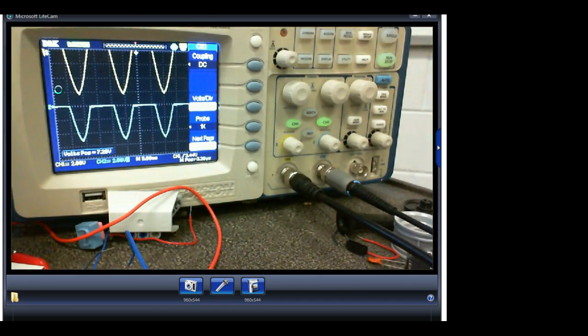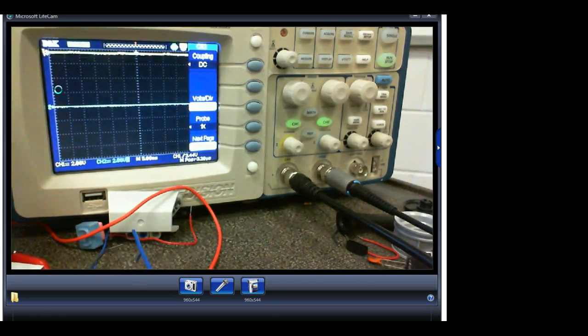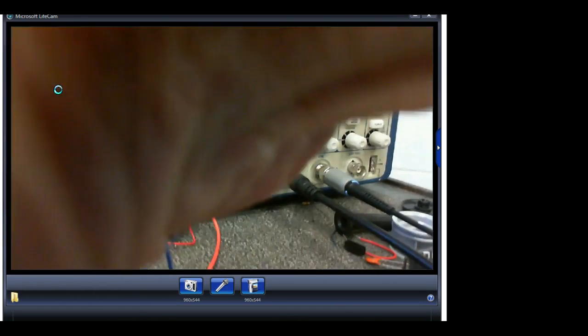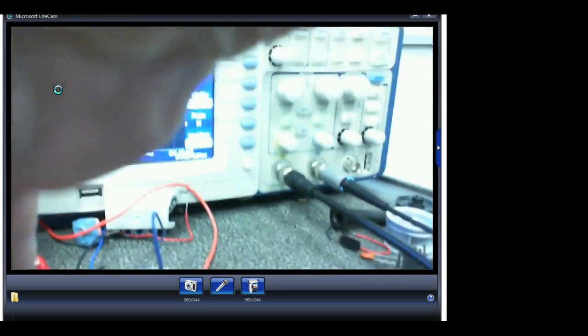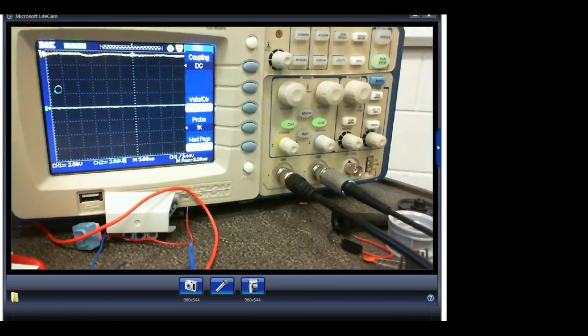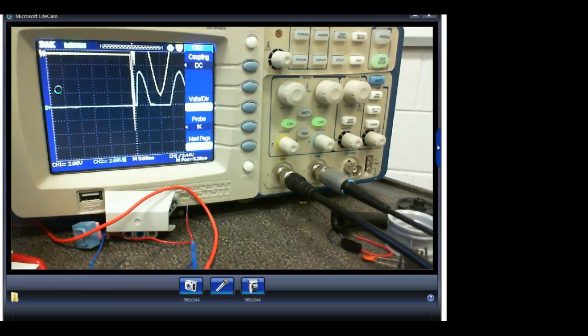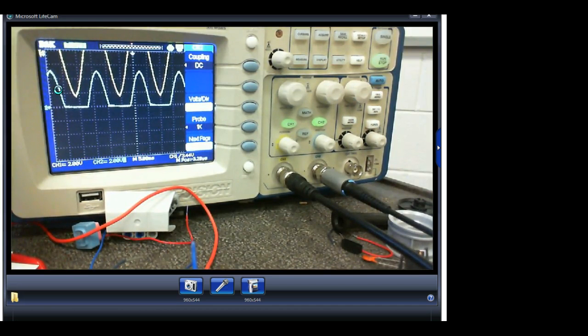There it is. How would I turn it into a positive supply? All I'm going to do is come over here and flip the diode around. I'm sorry, I lost my... Put my power source back up, my meter back up, turn it back on. So now the anode is pointing back toward my function generator, and it's a positive supply. A while ago, my cathode was pointing back, and it's a negative supply. And that's all we have to do to get a positive DC supply.